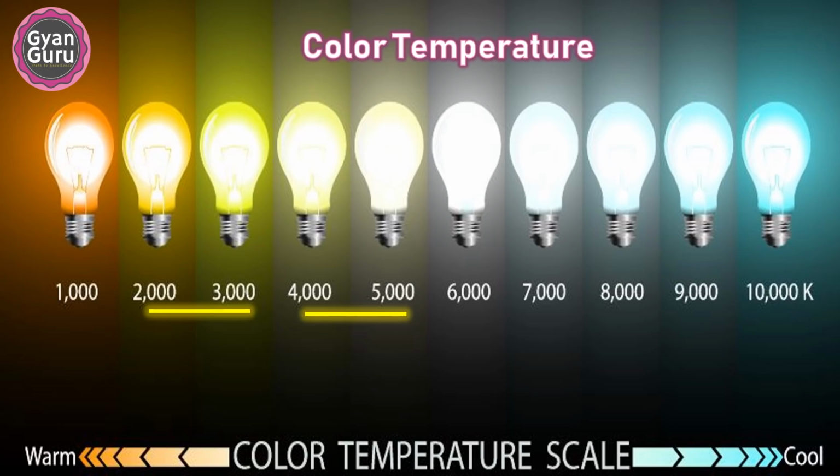As you move up the color temperature scale, you will get some yellows starting to show up and some more bluish white light. As we move forward on the spectrum from 5000 Kelvin to 5765 Kelvin, the light looks very white to our eyes, a crisp, clean-looking light that is appealing for modern spaces, paint booths, gas stations, hospitals and office environments. And above 6500 Kelvin, the light will have a similar color to that of natural light outside. Daylight gets into the blue spectrum and you start seeing less of the yellows and whites. You will still have what appears to be a bright light, but when compared to full spectrum you can visually see the blue light starting to take over the color of the light.